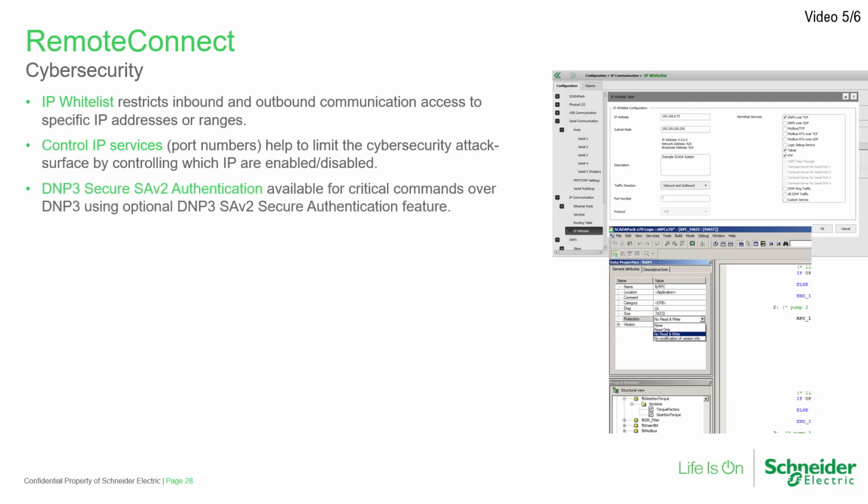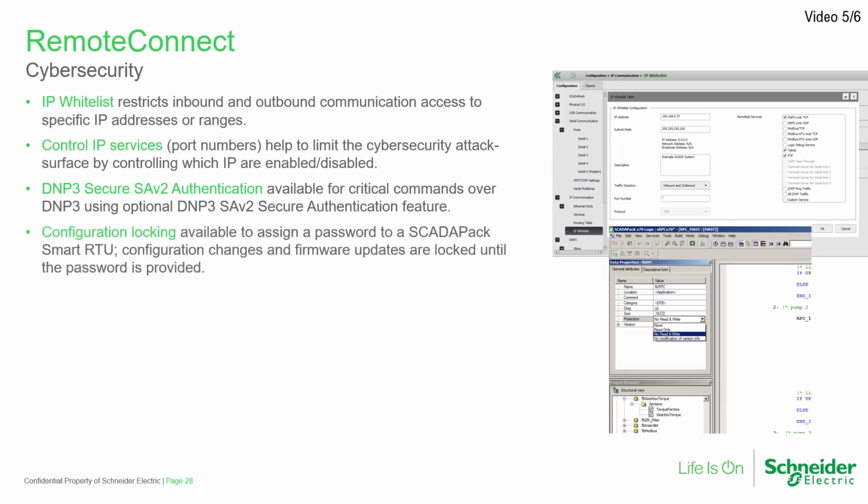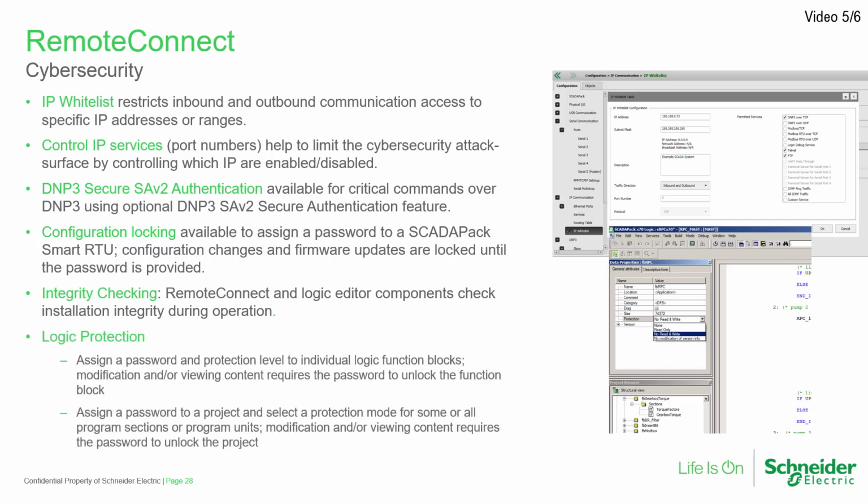an optional DMP3 secure authentication feature that's available for critical commands over DMP3, configuration locking, available to assign a password to a SCADAPack Smart RTU that locks configuration changes and firmware updates until the password is provided, integrity checking, in which RemoteConnect and Logic Editor components check installation integrity during operation, and logic protection, where a password and protection level is assigned to individual logic function blocks, or to a project where a protection mode can be selected for some or all program sections or program units.